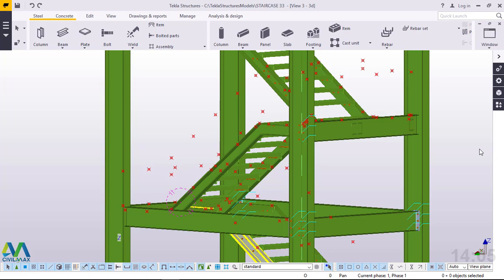Today I'm going to show you how to fix handrails to a staircase tower of this kind with the help of points or coordinates placed with your preferred dimensions of handrails, and these are placed manually.